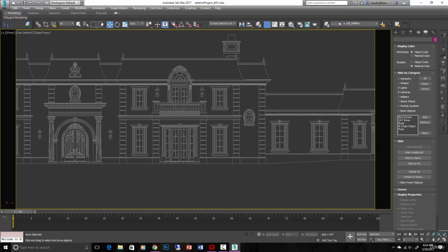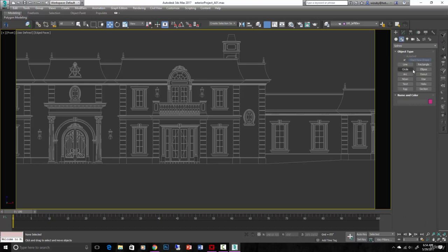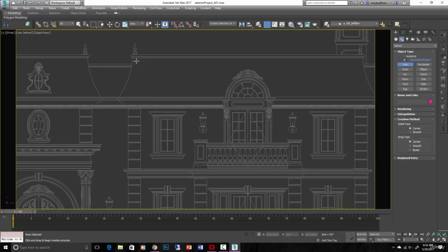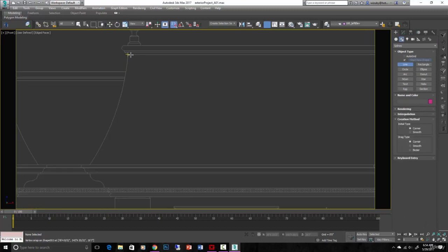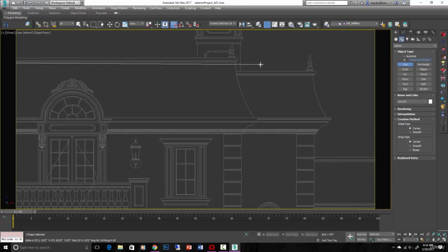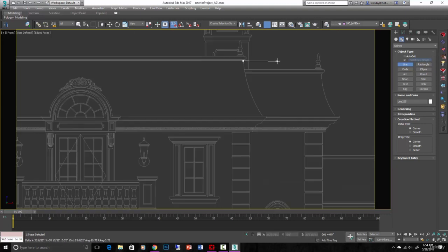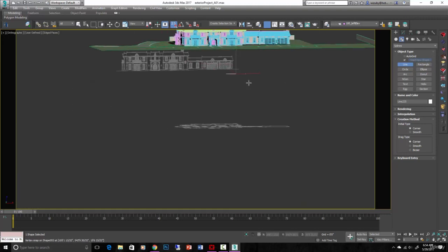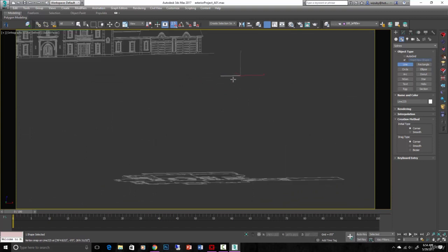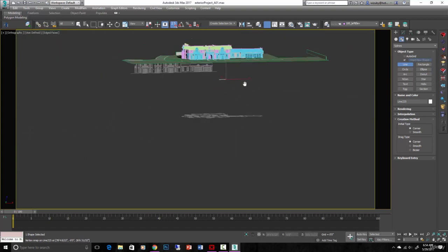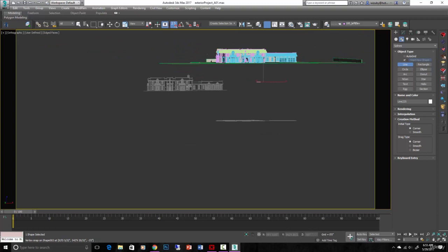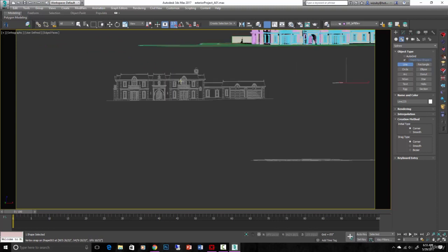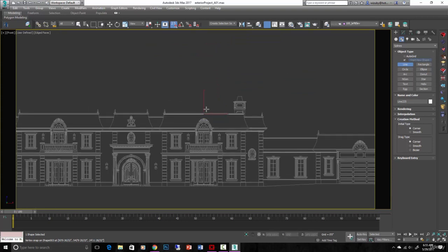You want to be in 2.5 snap. What that does is when you draw a line, it will snap to your CAD, but not in depth. What happens is this line is drawn at 0, the 0 plane in the y-axis, and the CAD remains way back there in the background. So you're not drawing right on top of the CAD, but you are still snapping to it in 2 dimensions, but not 3.